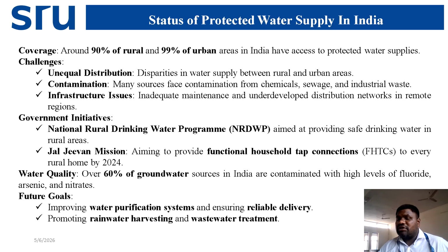Next, the purified water will be sent to the next chamber, that is a skimming tank. Here whatever oil and grease there is will be stopped and will form a layer at the top of the surface water, so we can remove it easily. The next one will be the primary clarifier. Here the remaining suspended solids, and some portion of BOD also, will be removed.